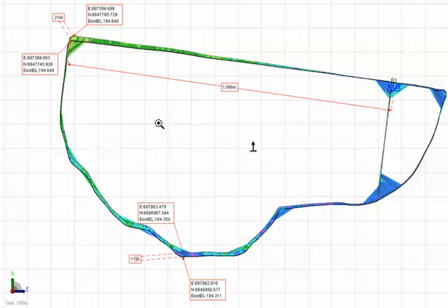Now the problem that produces when we try to survey with one coordinate system, do a design, and then export back out to load into another GPS system to do the earth moving, is that these differences can end up producing significant differences in what the design should be.